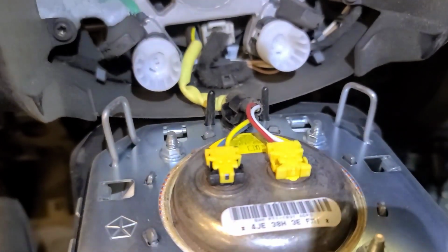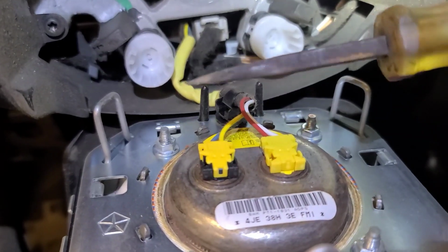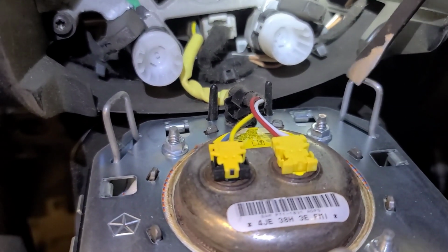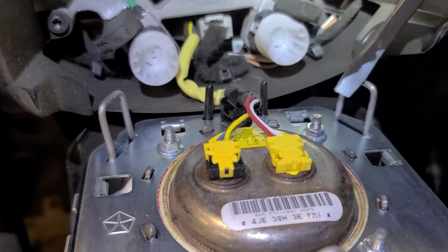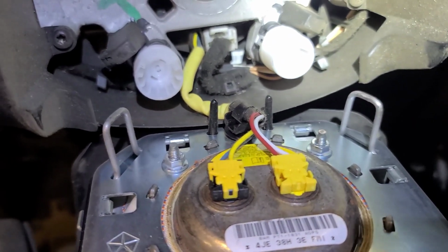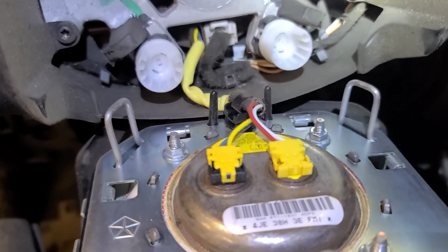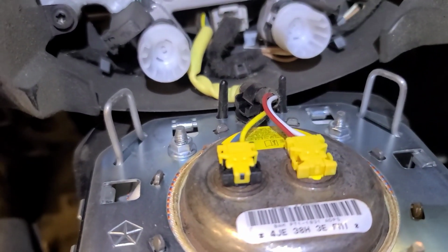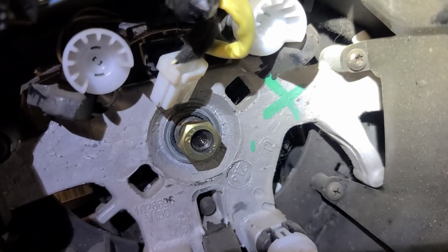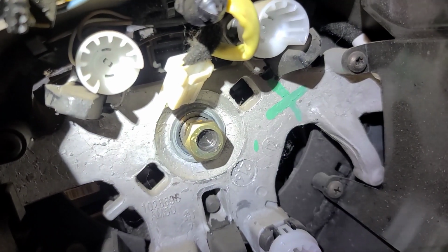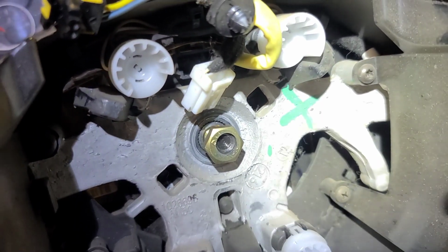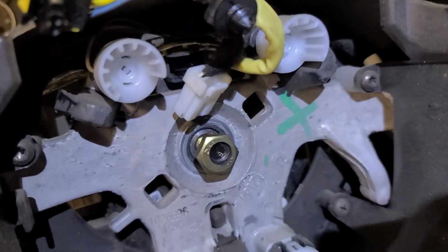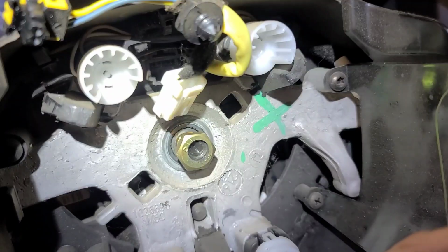So I found the best thing to work was about a 6-inch long, 3/8 wide screwdriver. Go in like so and turn it 90 degrees and use a mirror to look in the back of the steering wheel. Disconnect the battery before doing this, by the way. Well, you would think I would be able to just pull the steering wheel off, but they obviously have some kind of 2-jaw puller that fits in these 2 holes. I have a small puller, but it won't go in those holes.